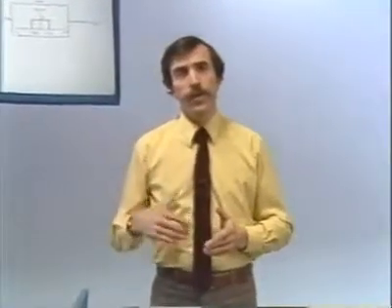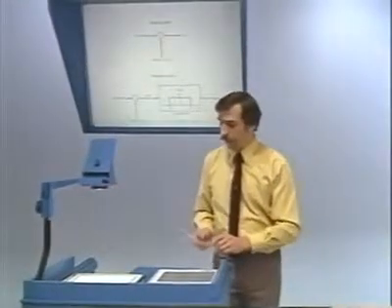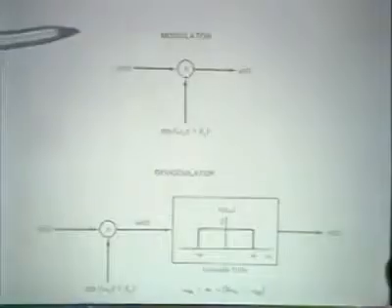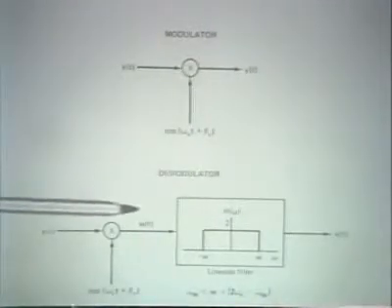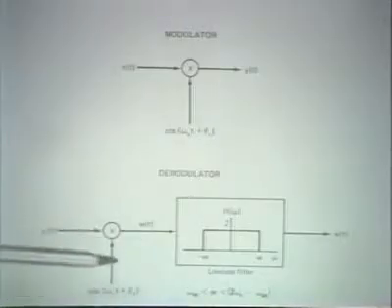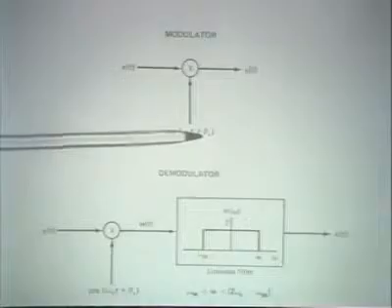And the reason for the term synchronous is that what's implied in these systems is a synchronization between the transmitter and receiver. In particular, in the system as we've talked about it, the modulator and the demodulator have a synchronization in both frequency and phase.